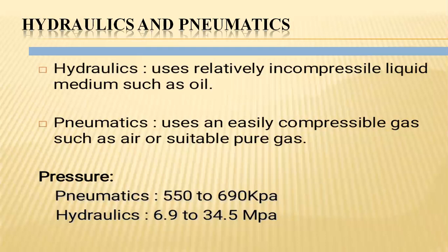In hydraulic systems, high pressures can be imparted and utilized for the work: nothing but 6.9 to 34.5 megapascals of pressure can be imparted in hydraulics, and hence, due to this basic pressure range capability, we can clearly differentiate the working nature of the actuators.